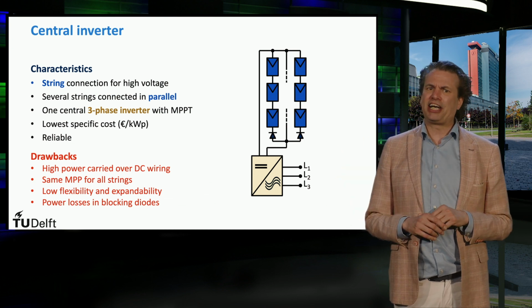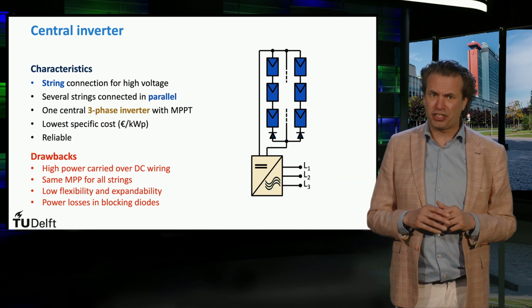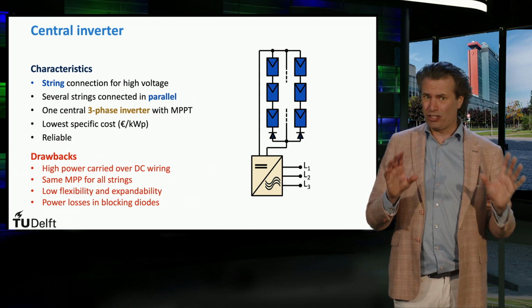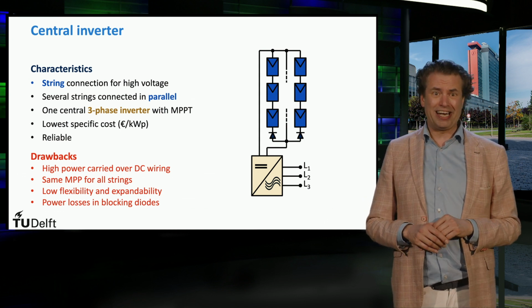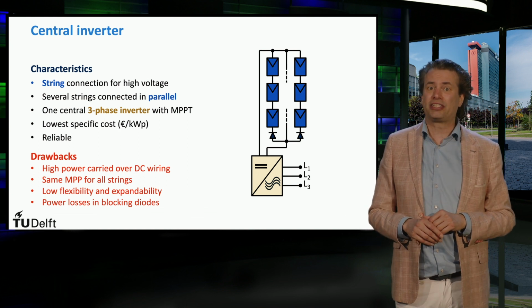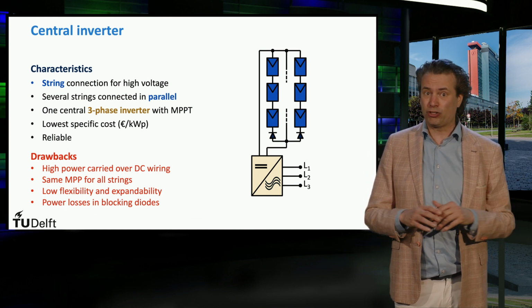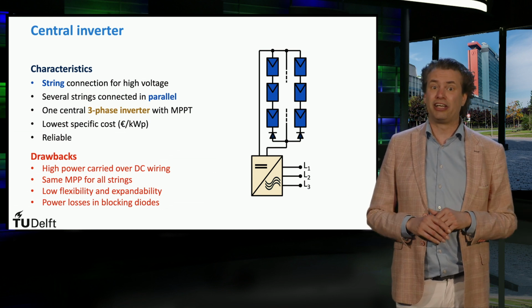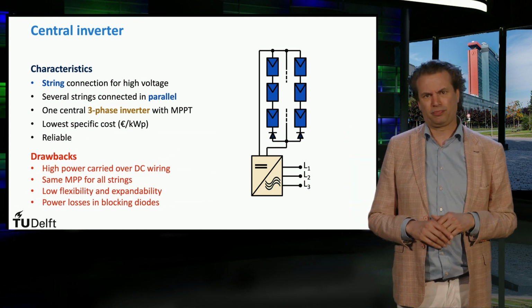Therefore, the engineer has to carefully choose the type and thickness of DC wires, because this can cause safety issues related to fault DC currents, and the need for thick cable insulation and special circuit breakers can lead to significant cost increase.